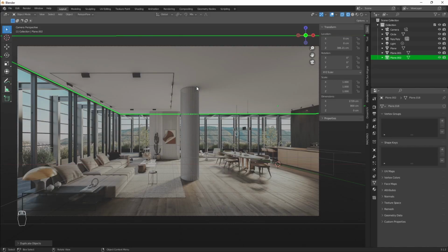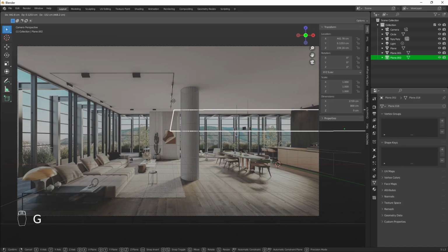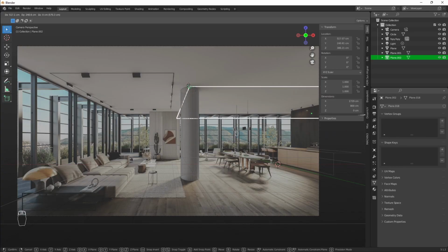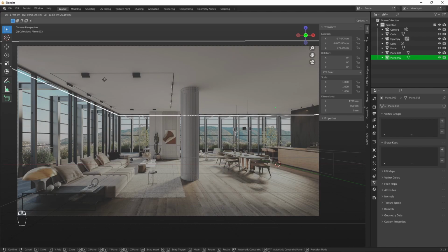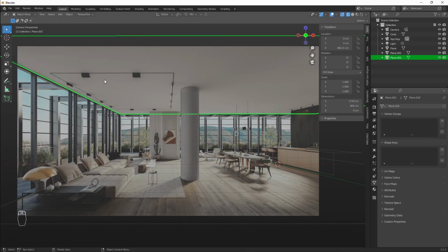By the way, you might have noticed that I haven't used this button to toggle snapping. Neither have I pressed Shift-Tab to activate it. And it's because Blender has this neat option. When you drag anything, you can press and hold the Control key and it temporarily activates the snapping mode. I use this frequently because it's less clicking, and sometimes I realize I need to use snapping when I've already started dragging, so without this little shortcut, I would have to stop it, turn the snapping on, and then grab my object again. But with this control key, I can use it anytime, and it's really convenient.